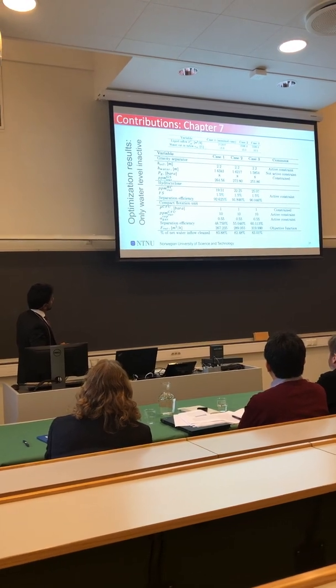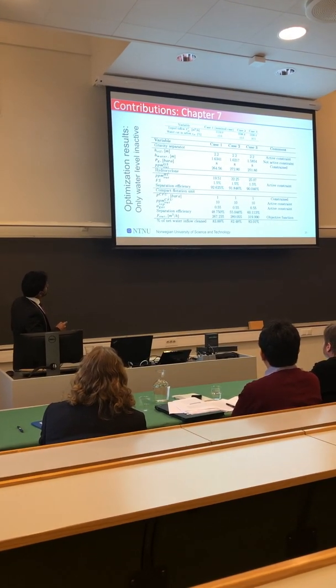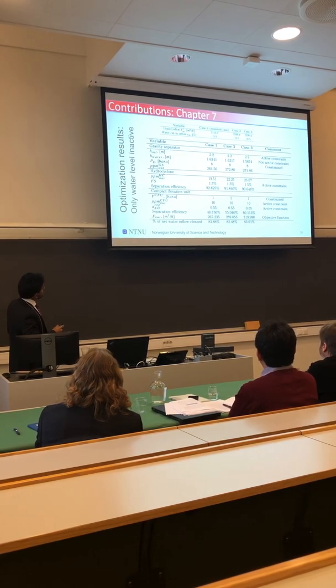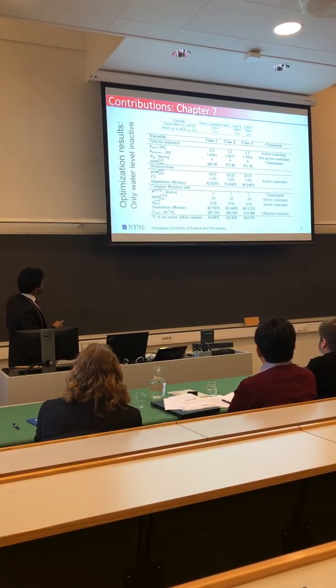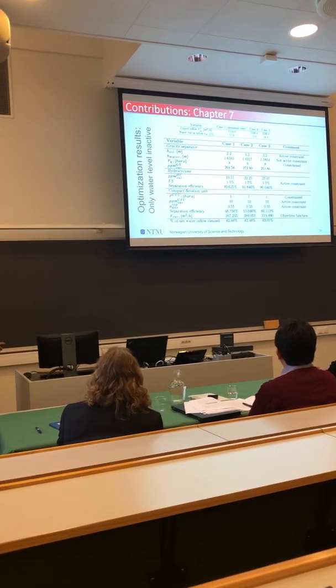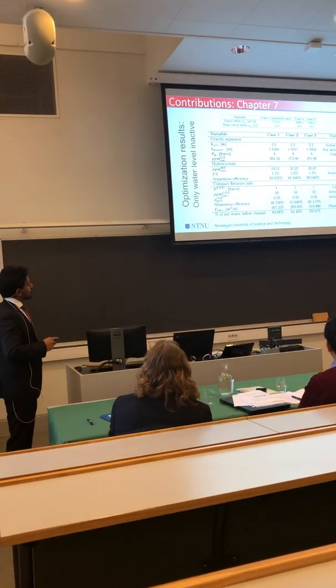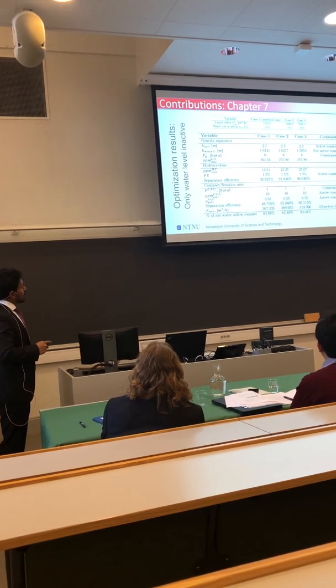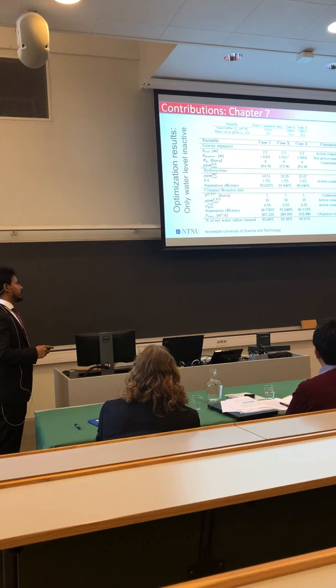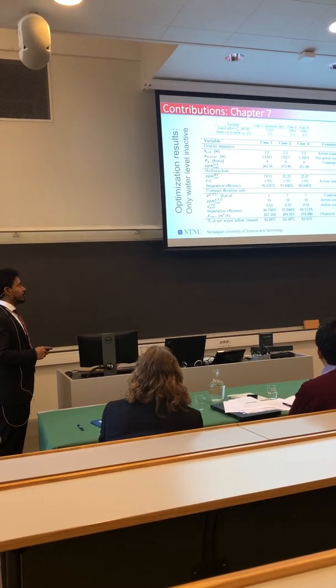And here I also show the different control variables in the gravity separator and the ppm in the water outlet. I also have the hydrocyclone. Here I show how much ppm is going out in the hydrocyclone, and the flow split that we have. It goes to the lowest flow split. It was between 1.5 and 2.5. It goes to the lowest.